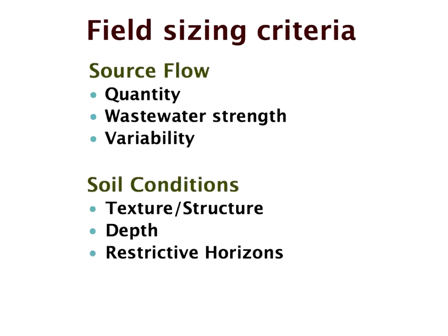So with primary effluent, you have that extra factor to look at, which is the risk of an anaerobic zone, which results in a larger area, often a very much larger area, and I would often say more drippers, so that each dripper gets a considerably lower loading of the anaerobic bacteria through the drip system. And if you know your soils correctly and it's designed right, it can and does work, but it's one more factor and one more risk that has to be considered.